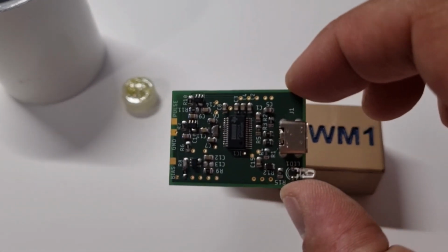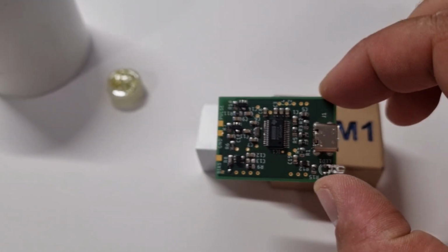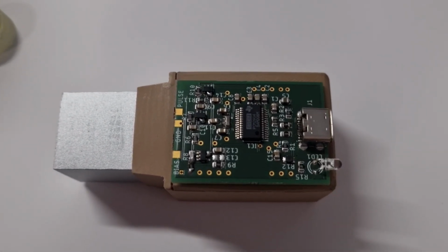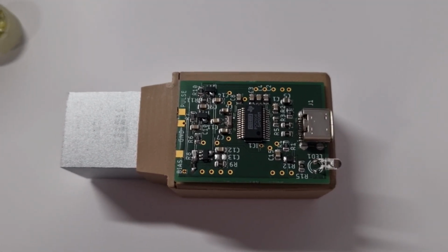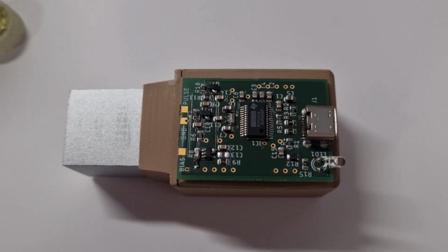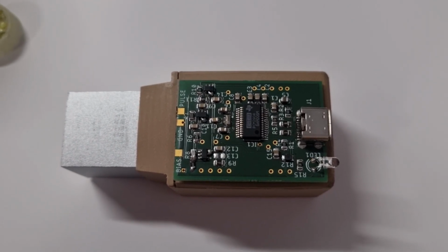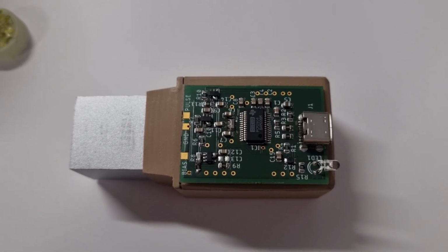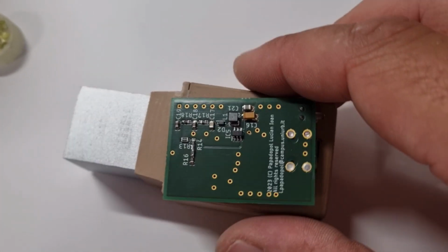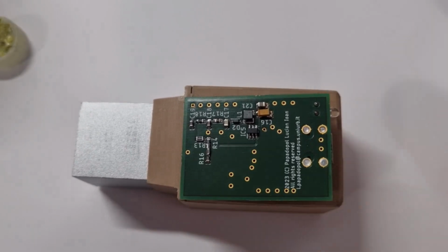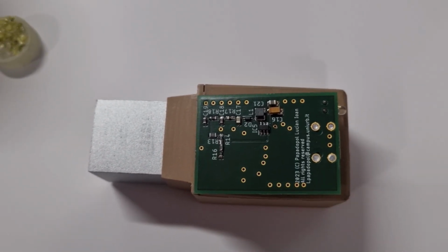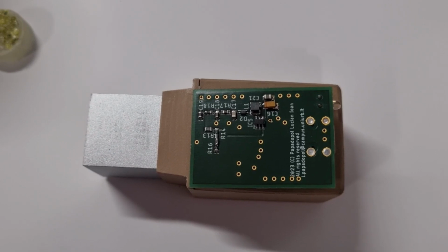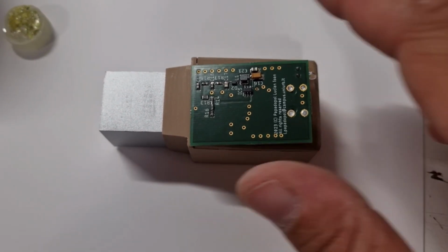This is the circuit with an audio codec which captures the pulses and sends them to the computer. And on the left you can see 3 op-amps that amplify and shape the pulses coming from the SiPM. On the lower part, on the other side of the PCB, you can see the voltage converter that generates the 40 volt bias for the SiPMs.